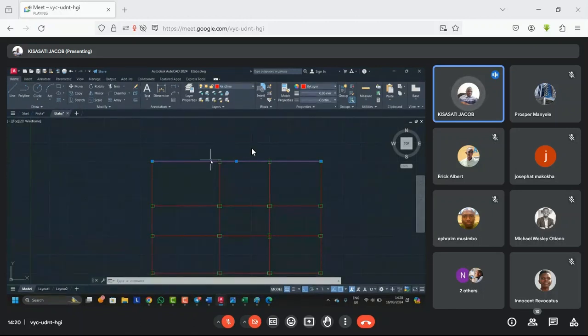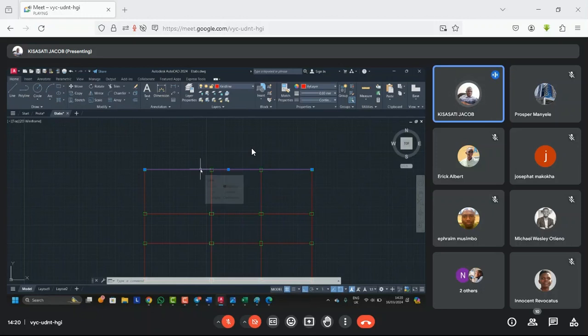But now pay attention to this. I have selected this one beam. As you can see, it's just a continuous beam from start to end, which is a very wrong practice. The good practice will be this beam will come from this column to this column, from this column to this column. Then after that, ETABS will now do them perfectly. Now, how do we break these beams to come up with the splits? How do we do that?